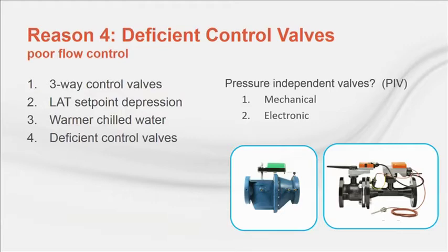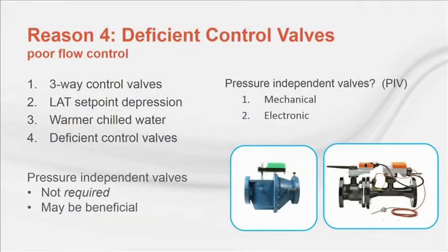Both can work equally well, and each has its own set of advantages. The question is, are pressure-independent control valves needed to assure good system delta T? This is a question of much debate among engineers. My answer? No, they are not required to get good control, but they sure do make it a lot easier